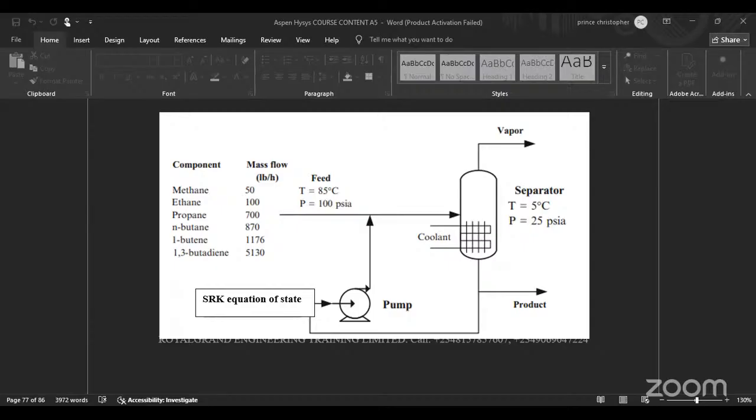So I'm going to double click this and use SQ as the energy stream. Outlet, I'm going to use liquid. I'm going to use vapor. Here, I'm going to use mixed feed. Now, it says unknown duty. Why is it saying unknown duty? It's saying that with the information I have, I can't calculate the power this separator is going to use. Remember, we specified an energy stream, the energy needed by this separator. You can see the energy stream there.